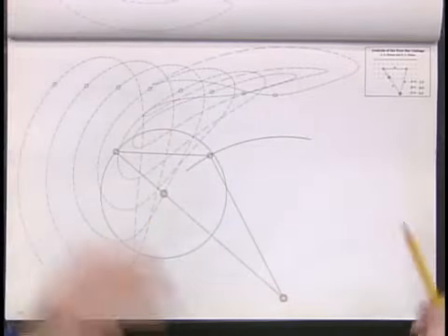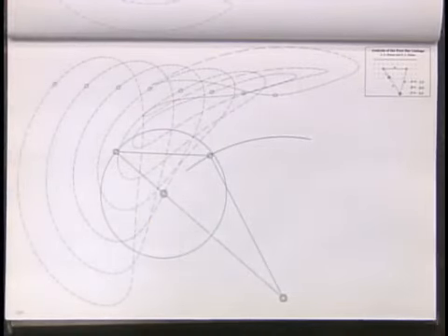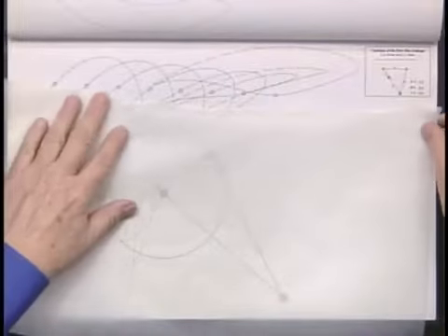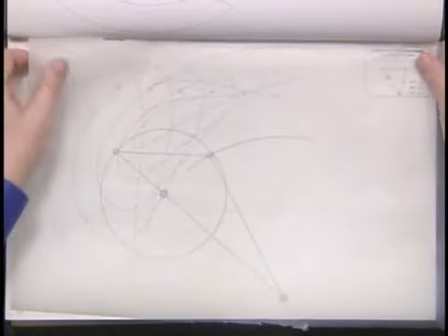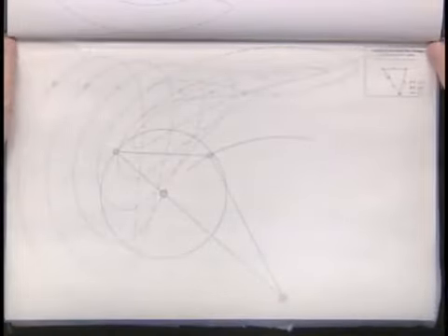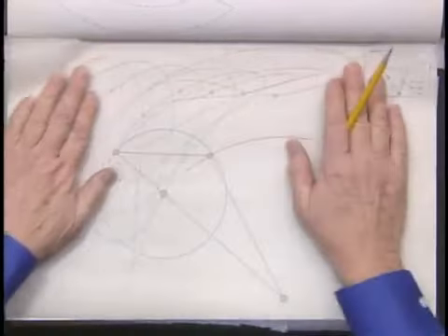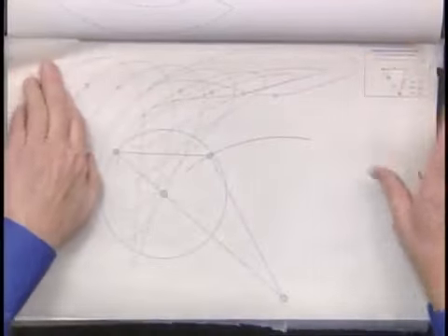So let's suppose that I'm attracted to that particular coupler curve, and I decide I want to make that linkage. How do I determine what the links should be? That's the next step. So I'm going to use a piece of tracing paper so I don't mark up this rare old book. And I'm going to need some drawing instruments for this too. That paper doesn't quite go as high as I would like, but I think I can get away with it. Okay, that's going to do. That's perfectly fine.